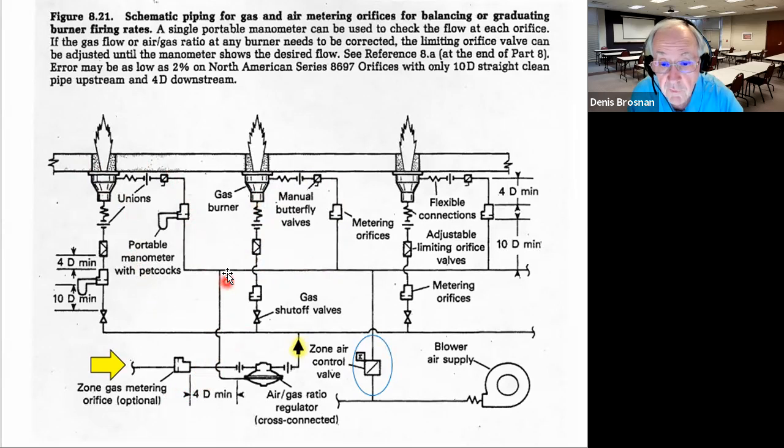I'm going to get this right eventually. There's the gas, and here's the air system coming in. So you can follow these lines better than I can looking into a computer screen. But here, an impulse from the air system is driving the ratio regulator on the gas system. We don't show any air or gas supplies for the pilot lights on these burners, just to simplify. They do show trim valves for controlling the flow rates on the gas and air systems.